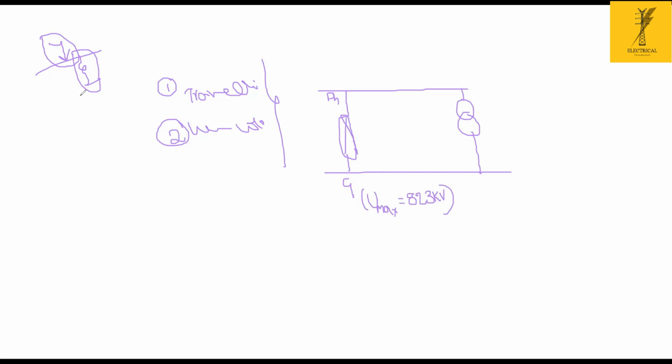So such a large magnitude does not appear on the lightning arrestor. If the lightning falls near the lightning arrestor, definitely it will fail. It's not able to handle that. That's the reason in high voltages and extra high voltages, we lay a shield wire on top of the transmission lines, because some part of it enters the grounding.